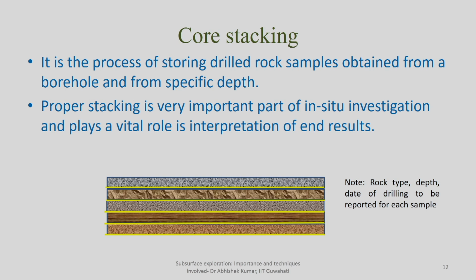So you can see here the core stacking. You can see in this picture, at different depths you had collected rock samples. On this you will actually write what is the rock type, what is the depth from which it is collected, and the date of drilling, when you started drilling, when you collected the samples. So you will actually write here rock type 1, and here 2, 3.